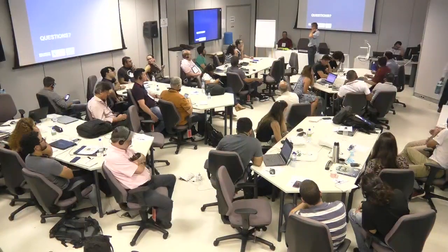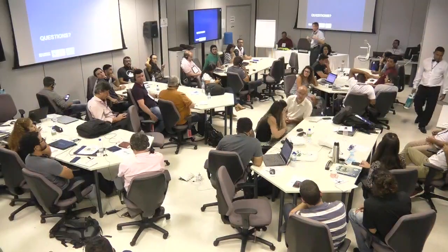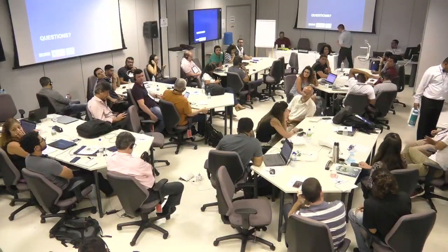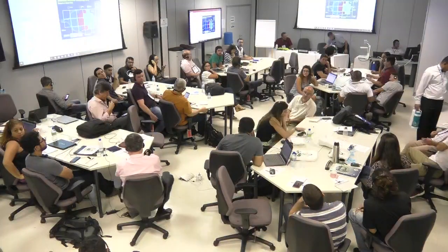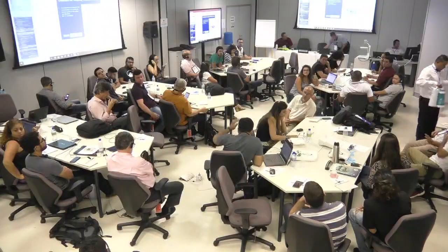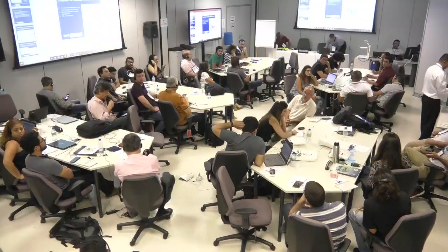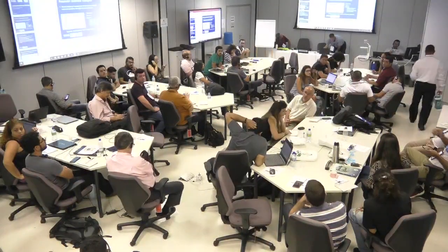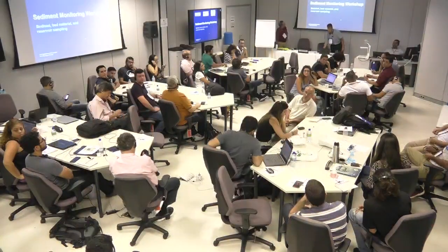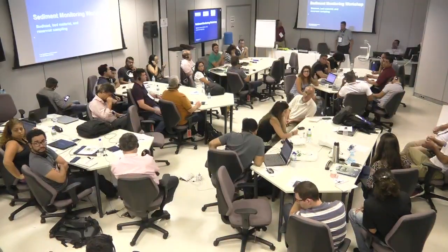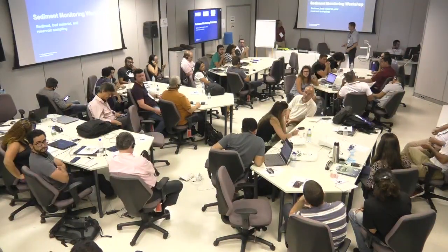So you want to take it? Well, I'm not sure I fully understand, but I think the question is, are you more interested in bed load or bed material? And if you are interested in quantifying the moving bed, which is bed load, then you would need to implement bed load sampling techniques to capture that. So that could be the pressure difference sampler lowered to the bed and collecting that sand. That could be an approach to collecting that information.